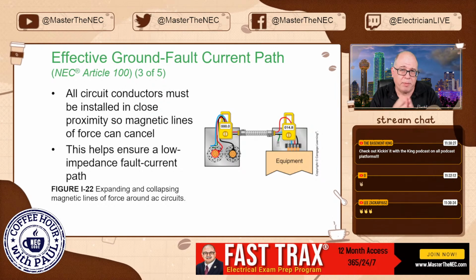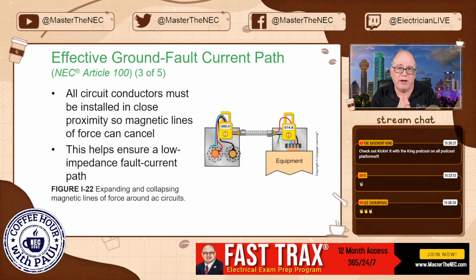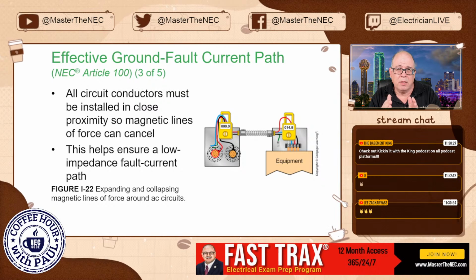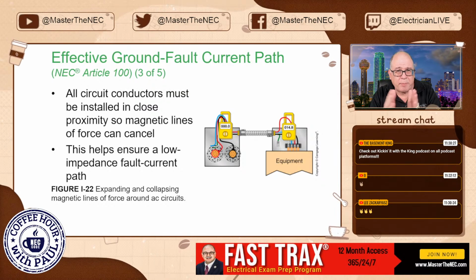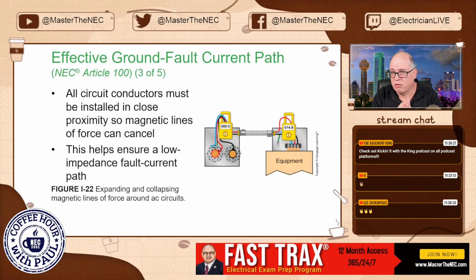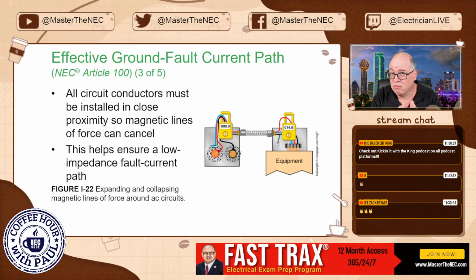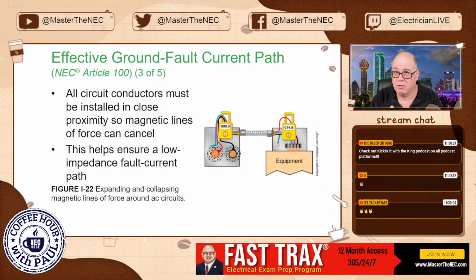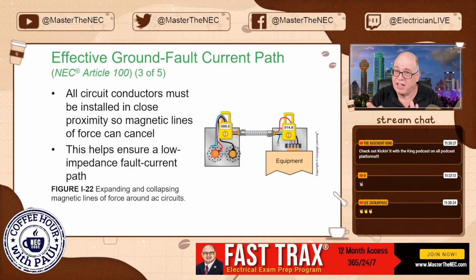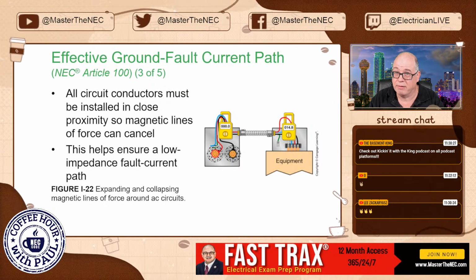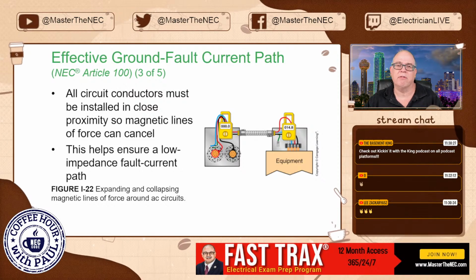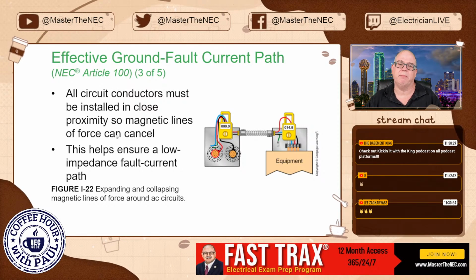When we say that when you're bundling more than 24 inches without separating, what is separation? 1/4 of an inch? 1/8 of an inch? 2 inches? A tenth of an inch? Code doesn't tell you. But I can tell you if they touch, then they ain't separated. I'm just saying.